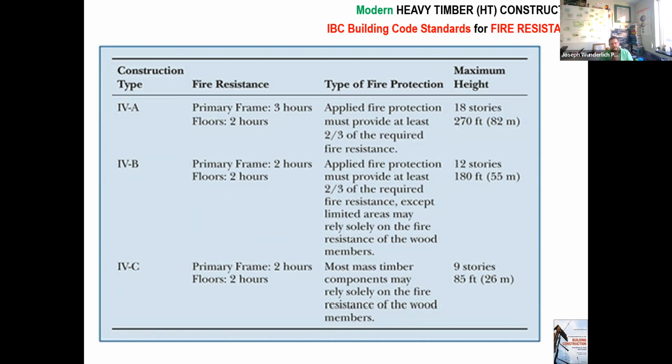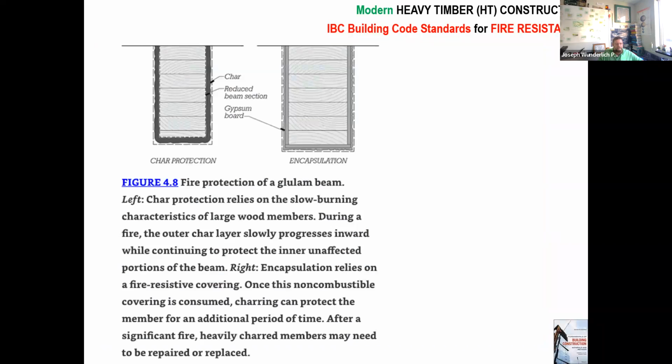The fire marshal will inspect drawings, especially in California, but everywhere actually now, where you have to prove that your building won't kill people when it catches on fire. And so you have places where people can escape readily, get out of the building, access points, as well as materials that will take a certain amount of time to burn, so the place doesn't collapse right away and the fire doesn't spread too fast. And then a couple of different methods of doing that.